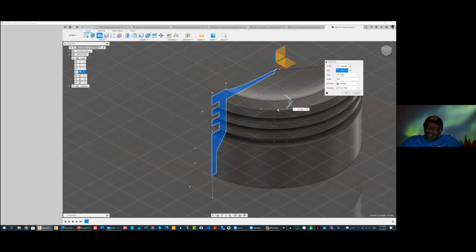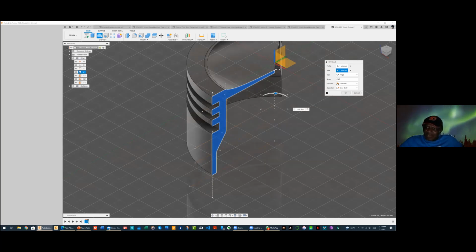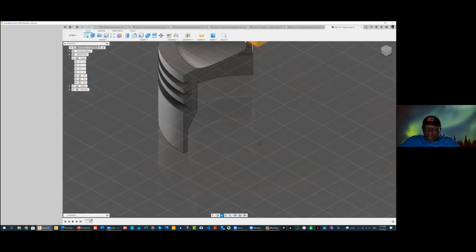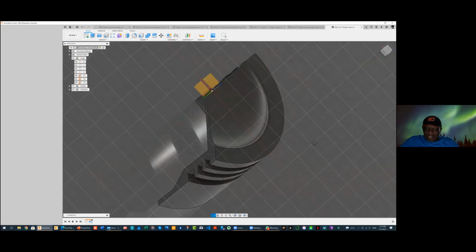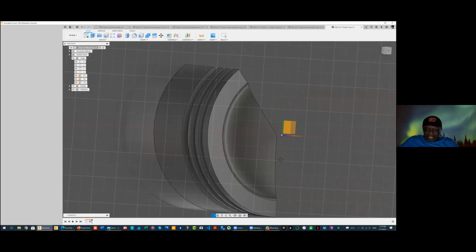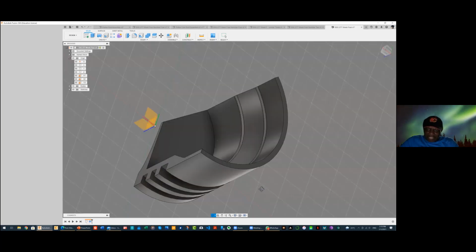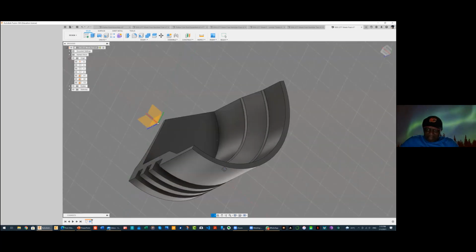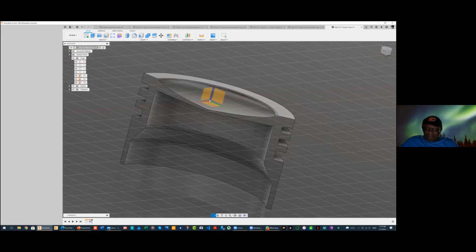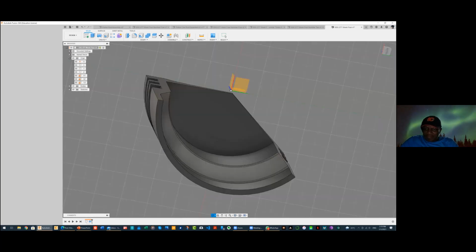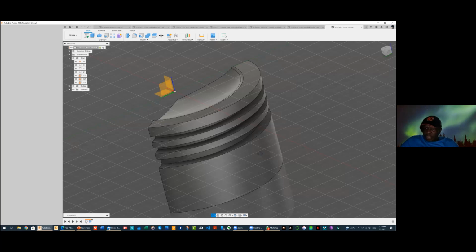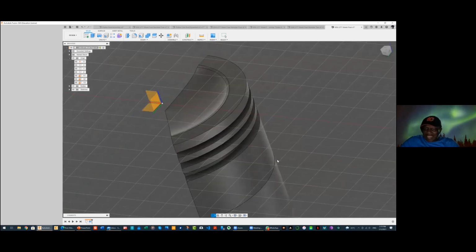So you can have a revolve. Let me accept this and you see what you will have got. So the revolve doesn't have to be a complete circuit. You can see the object we have created. If we do not use a full circuit, we can revolve and create a partial dashpot, a partial piston here. So this is a piston subtending an angle 140 at the beginning and at the origin.